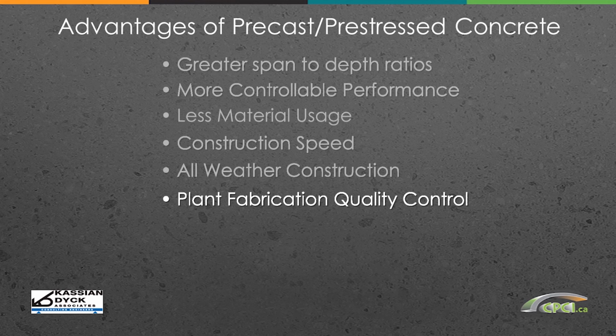With precast concrete, you also get the benefits of improved quality control by constructing elements in plant-controlled conditions that provide increased reliability of construction. In fact, that's recognized in the Canadian Concrete Design Standard CSA A23.3, where designers can take advantage of the increased strength capacities of precast concrete as compared to cast-in-place concrete construction.